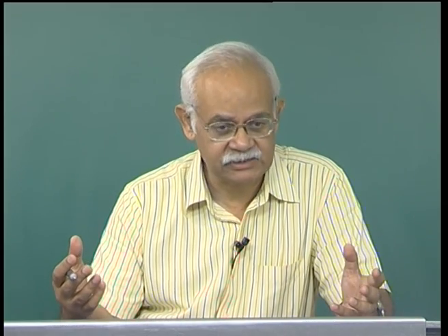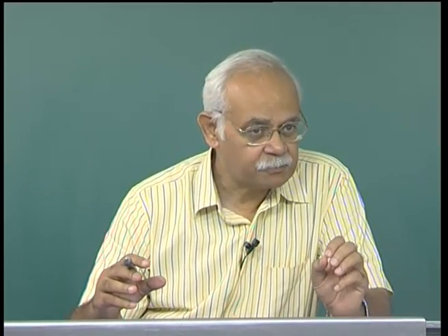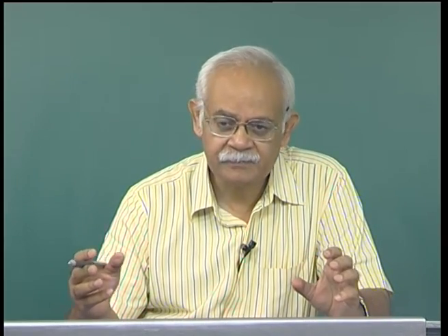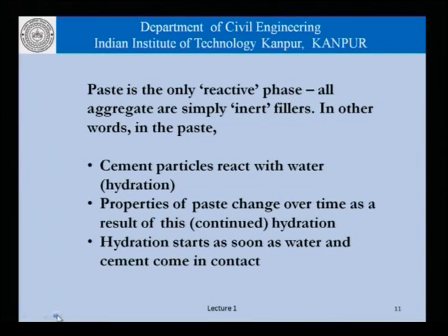It's not a paste in the sense that we have water and we have certain particles suspended in it, and the properties of that composition or that composite do not change with time. In this case, we have those particles reacting with water all the time, or at least till such time as the hydration reaction is complete, and this reaction leads to consumption of those particles and formation of new hydration products, and that alters the properties of the paste. So once we understand this, it helps us greatly in understanding the properties of concrete in all senses.